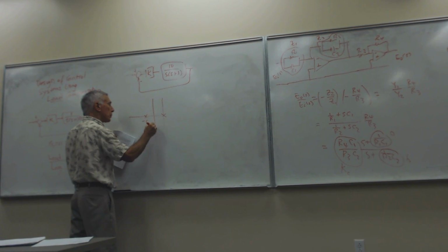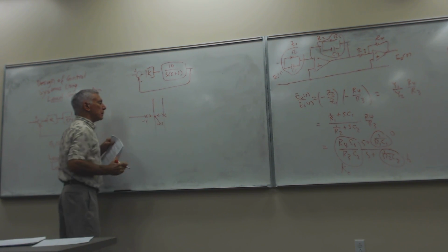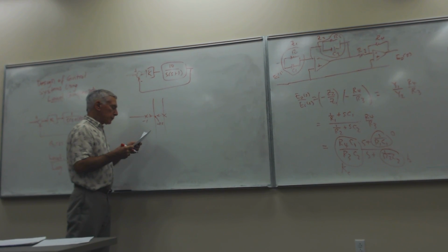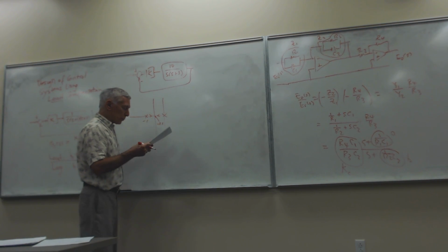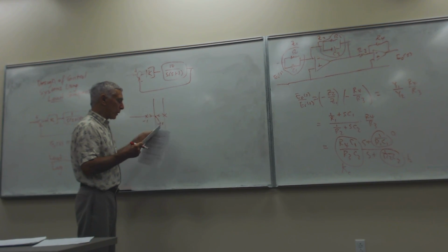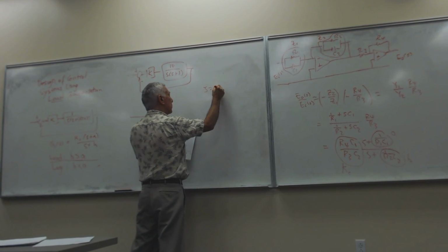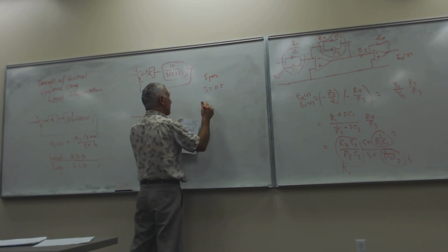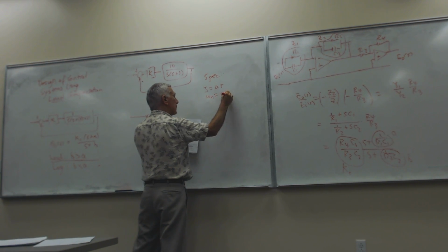And so the root locus would look like this. And the breakaway would occur at -0.5. Okay. Let's say that you would like a closed loop transfer function pole such that the damping ratio zeta is equal to 0.5. So this is the spec damping ratio, and the undamped natural frequency is equal to 3 radians per second.